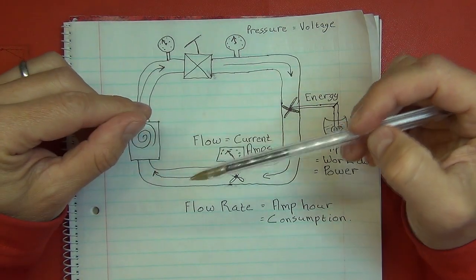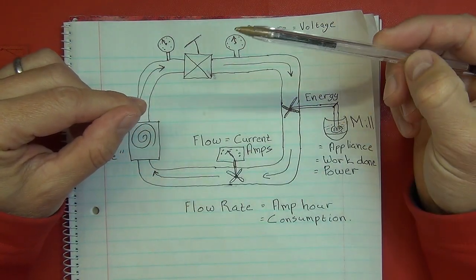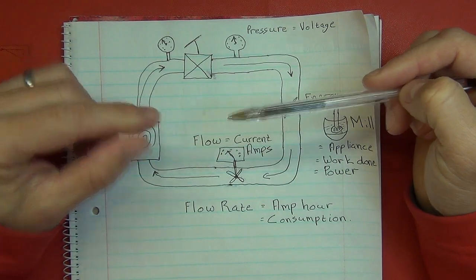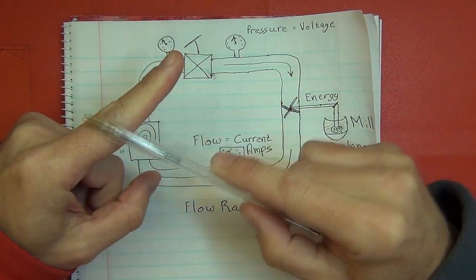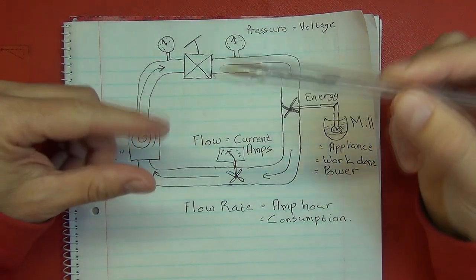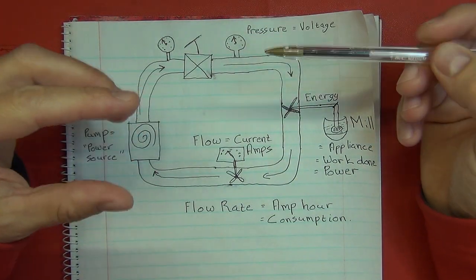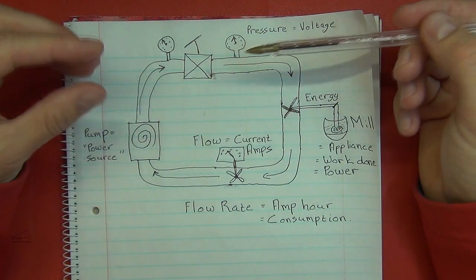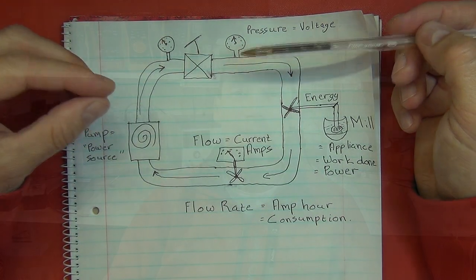So you can transfer high voltage at low current, so you don't need thick wires and you've got less loss, and then you transform that back to your normal voltage when you get to your house.